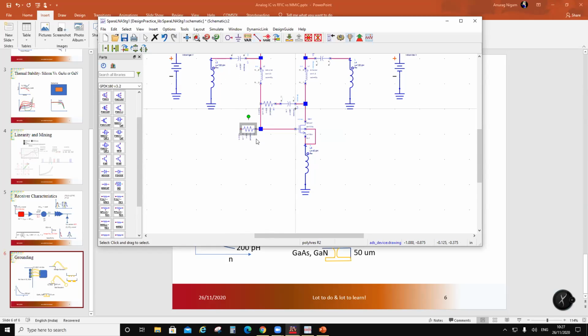If you want to do this, for your low frequency stability, you do this. But if you want to do this, do this. So you buy any transistor from UMS and you get their application note. They'll just put a resistor here. What about this bypass? This bypass has to be there, no?